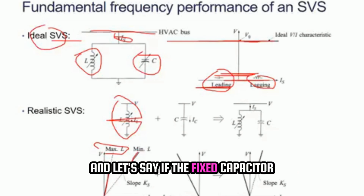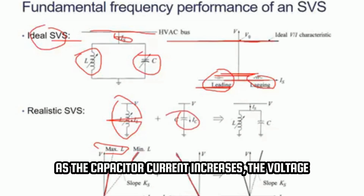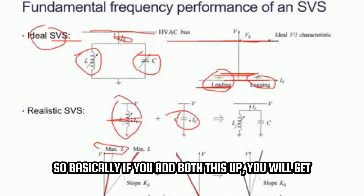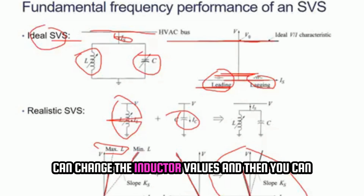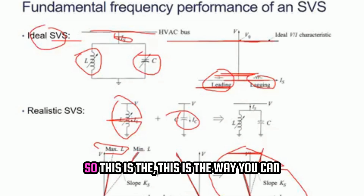Let's say the fixed capacitor is there, then what will happen? Because it's a fixed capacitor, as the capacitor current increases, the voltage is increasing at the left-hand side, and this is in the leading form. So if you add both of these up, you will get the final SVC system, where there will be a capacitive value and you can change the inductor values, and then you can get different voltage values as per the current. So this is the way you can actually control the system voltage.